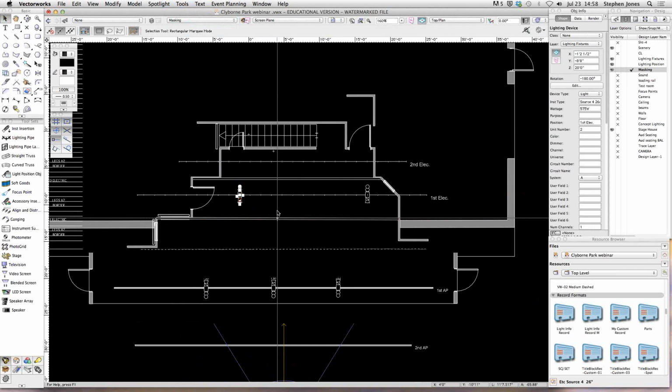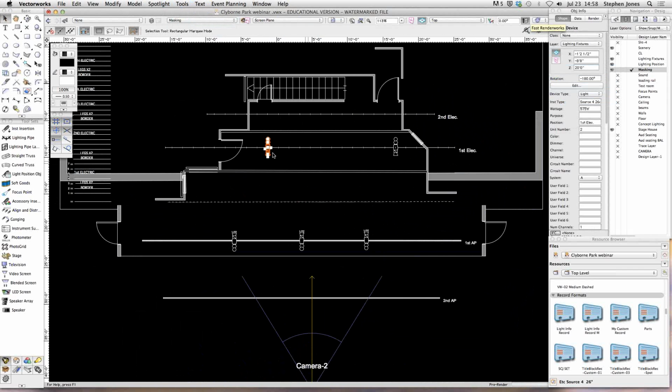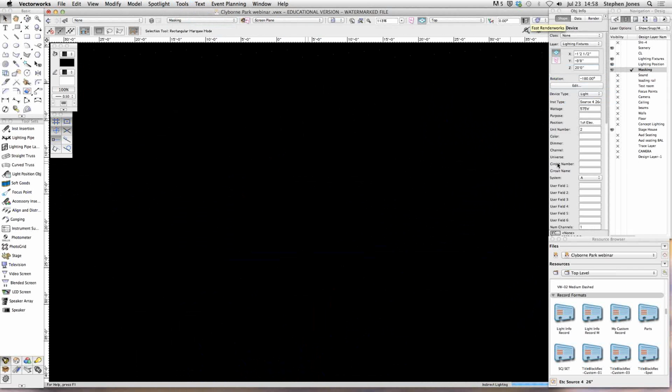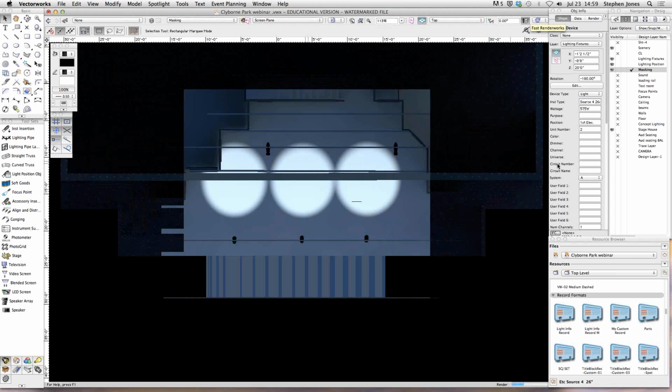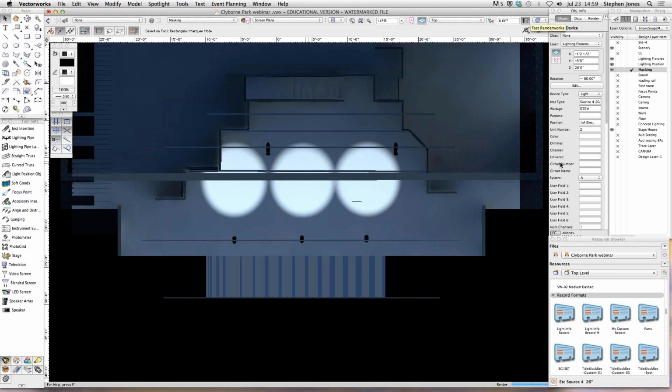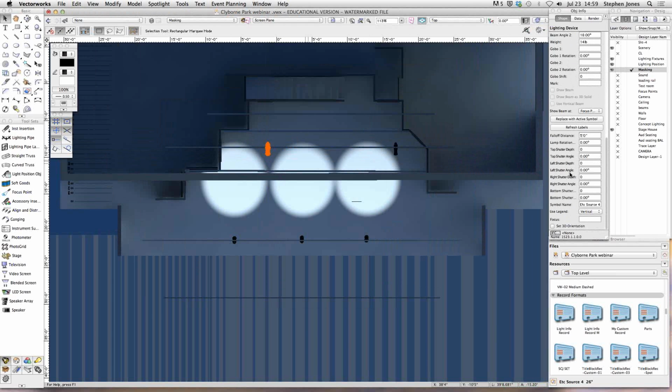I can show you very quickly under Fast Renderworks. Actually, this hasn't been assigned to anything yet. The key is you have to remember that when you turn on the light, it actually has to be focused towards something. Essentially that's how you do it. To review, you'd right-click, turn on, but the first thing you'd want to do is go into your Object Info palette and adjust the focus to, say, C, and then there you go.